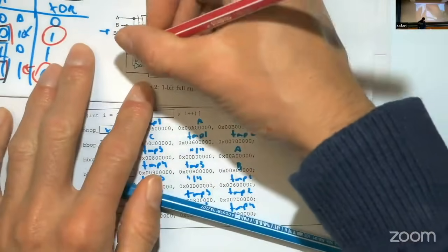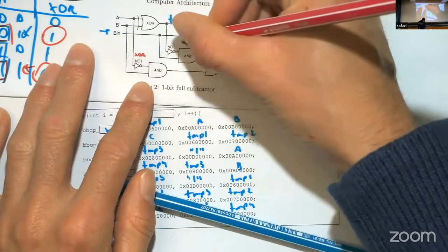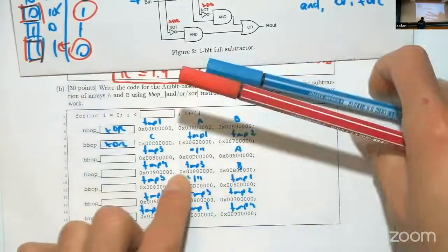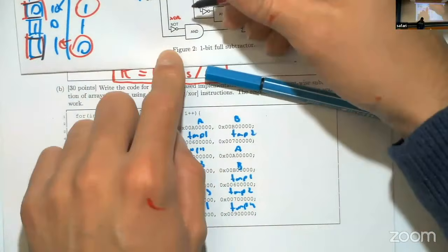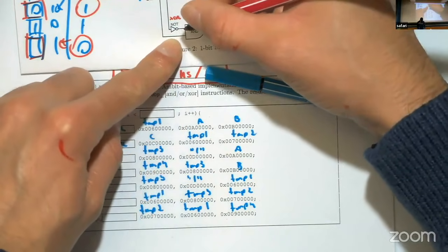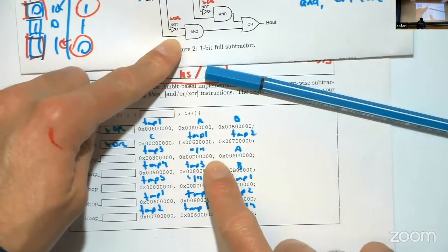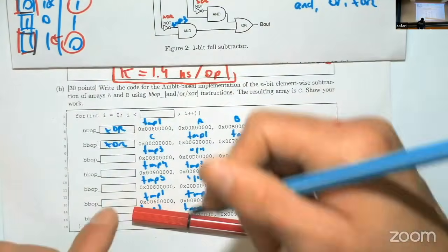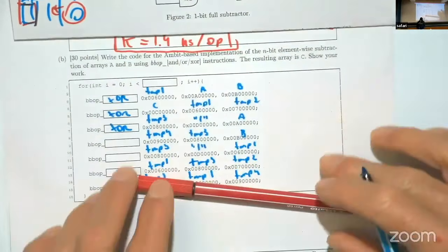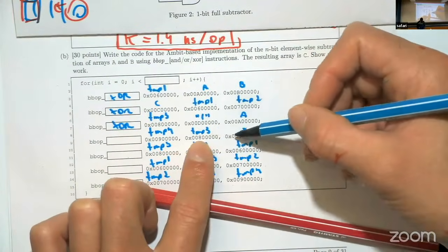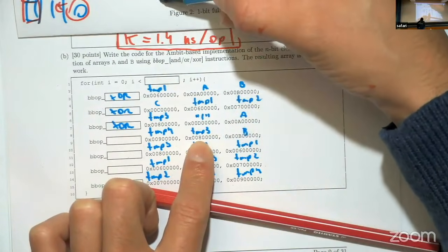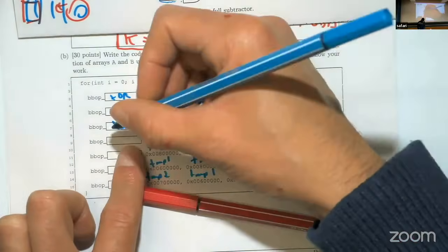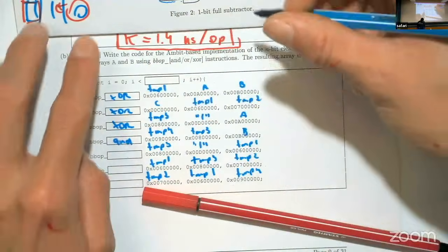So now you know that this NOT here is going to become XOR. This is going to become XOR. There are only these two actually. So this is one with A and a temporary. So this is definitely A here. This is definitely this guy here, right? And this is storing temp3. This is XOR. Then you have temp3 and B. So B here and temp3 is this AND gate here, right? So this is AND. This is temp4.